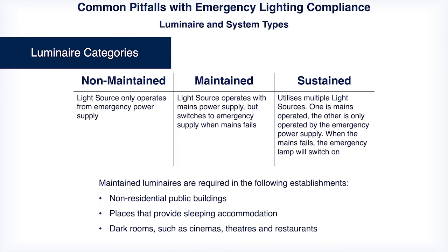So there we are. That's a quick summary of what we mean by non-maintained, maintained, and sustained. And typically, as I said, maintained are required in mostly non-residential buildings, so office buildings. Certainly all hotels would provide that, and then dark room areas as well.